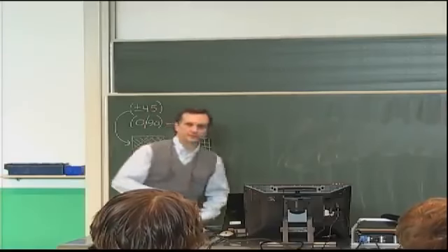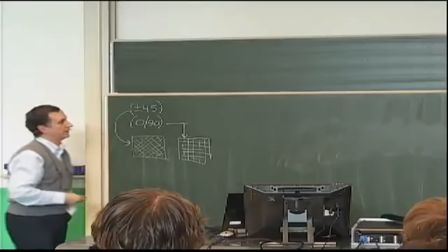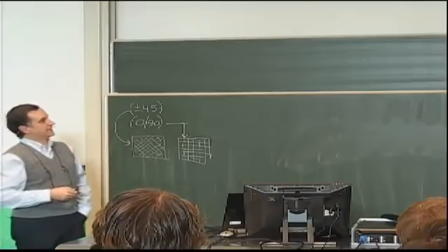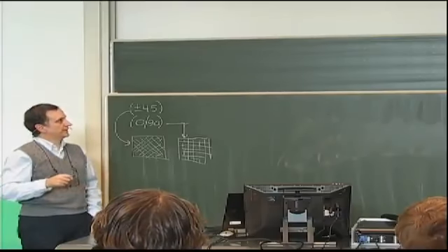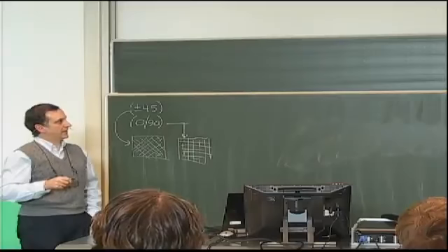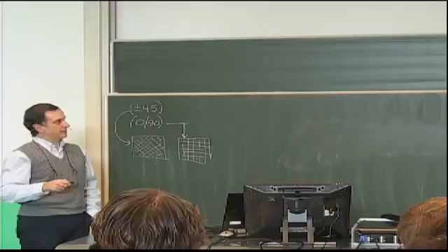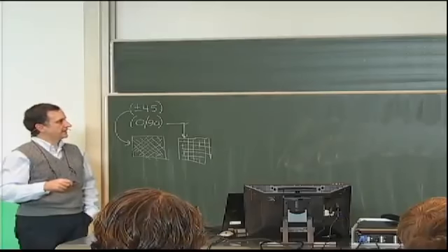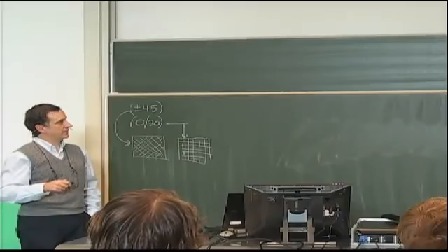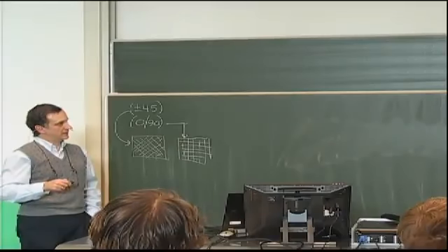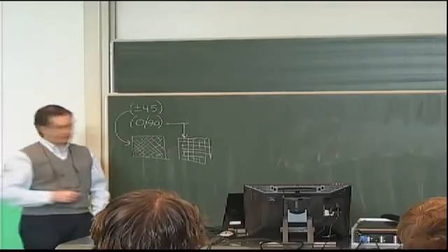If I'm taking all this now as a reasonable, good indication of the first sizes that I would need for reinforcement, I can summarize my conclusions: axial stresses in the 0.94 panels decay more slowly, so they would require longer doublers, while the other two faster. We just saw that. But the transverse and shear stresses in these plus or minus 45.4 and the plus or minus 45.090, the quasi-isotropic panels, are more critical in terms of the peak values.